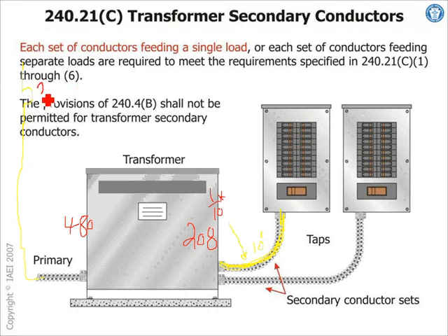Shall we give it an overcurrent protection device? Shall we use 300 amp here, just for the heck of it? 300 amp on the primary side. So we're going to tap this 300 amp. On the primary side, one-tenth of 300, multiplied by 480 divided by 208. Now we're taking the voltage ratio into consideration, multiplied by 300. That's the smallest conductor that you can pull here.